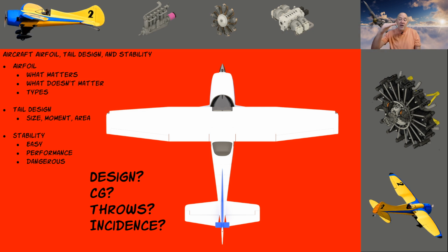But then I went home, and the rear of the wing where it connects to the fuselage, I dropped each of those 1/2 inch. And then from there on, the plane flew perfectly level. So what had happened was I had a flat bottom wing, but my leading edge wasn't really a Clark Y. The leading edge came almost all the way down to the bottom of the chord. So if I would have drawn a line through the angle of, well, the incidence angle relative to the thrust line of the airplane, I was barely above 0. That's the reason the plane needed about 2 to 3 degrees of nose up just to fly level.